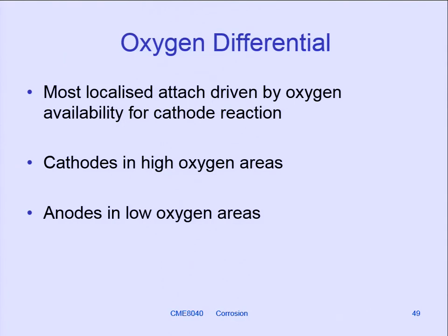Got another sample to show you. This again is a stainless steel pipe. It's a rolled pipe with a weld seam down it. What's interesting about this failure when it arrived was that the line of pits down the length of the pipe is offset about 90 degrees from where the weld is. So the pitting, the localised corrosion attack you're seeing, has got nothing to do with the heat affected zone and the weld, which is where you normally get the bulk of your failures. So something else must have been happening.